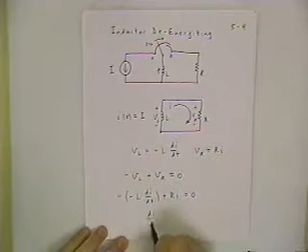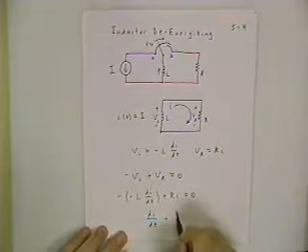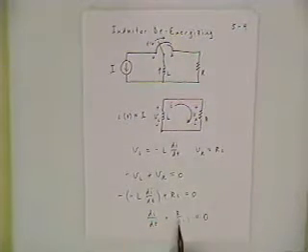And now we get our first order differential equation that reads di/dt plus R over L I equals 0. This is the same equation we had before, it's just the constant has changed. The time constant is a little different. So what we have to do now is the solution to that equation is again an exponential.